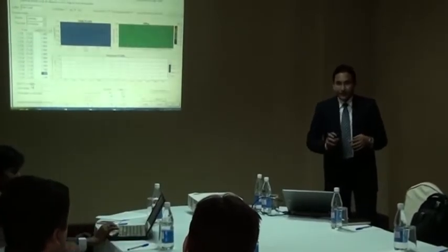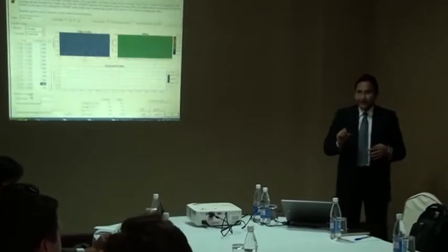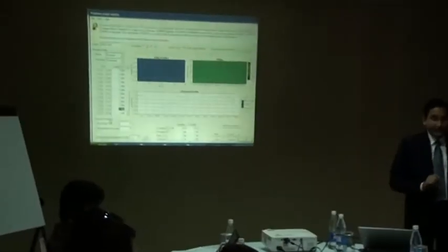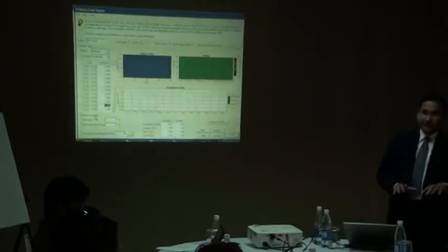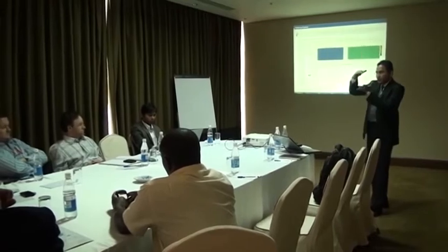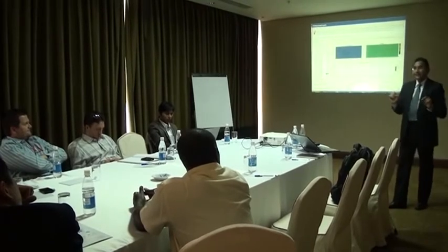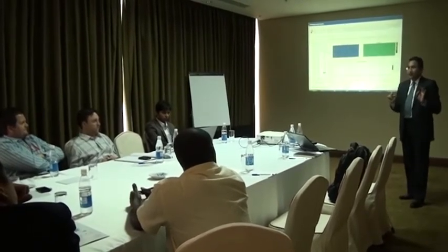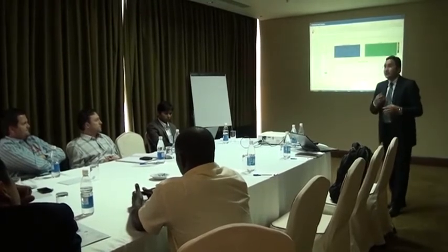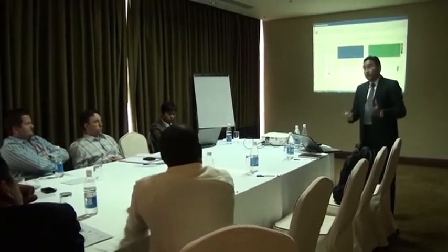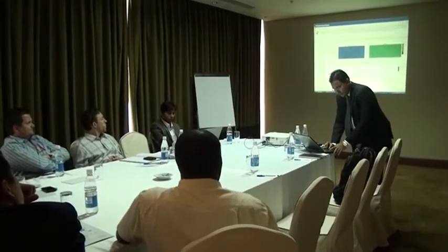So you're having a different sort of load profile, or maybe a little bit of variability exists in the site load requirement. Now, if we have a specific data, it's good, you can put it. If you don't have any specific data, what we always suggest is maybe you can go for a 5% variability. Is it 5% from day to day, or time step to time step? Time step to time step means 1 to 2 p.m. and 2 to 3 p.m. The two different time slots have a 5% variance of power requirement. So this is a very generic recommendation, 5%, but if you have any specific understanding of the load profile, you can go for that. So here we'll go for 5%.